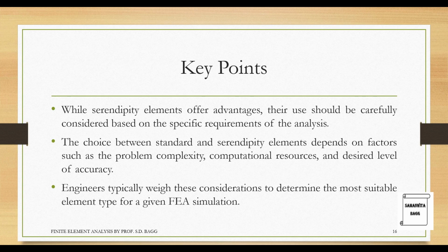Similarly, if your computational resources are really good, or if you don't have a problem of reducing the cost, or you're not finding it difficult to deal with a lot of computation going on, then you can use standard elements. Similarly, if your accuracy is not a problem, then you can go for standard elements. But if these three reasons are present with your problem, then you need to go for serendipity elements.